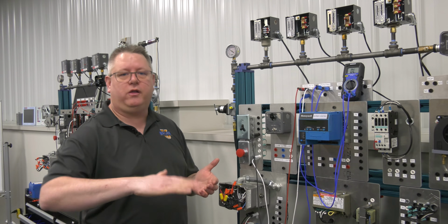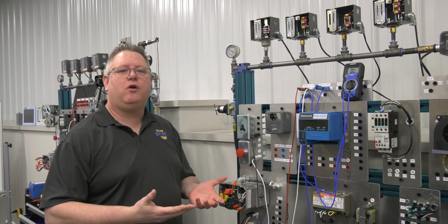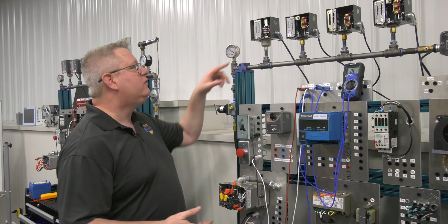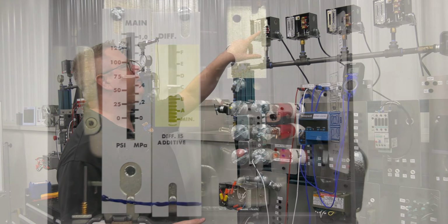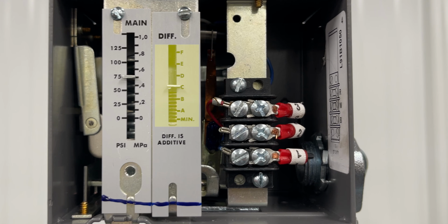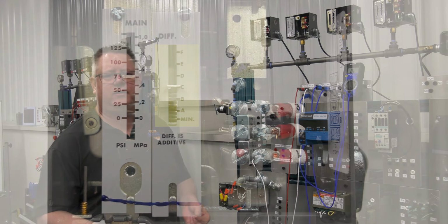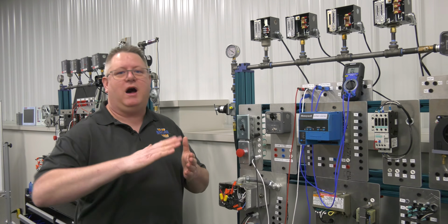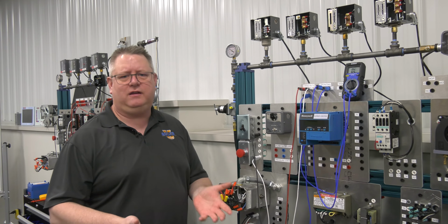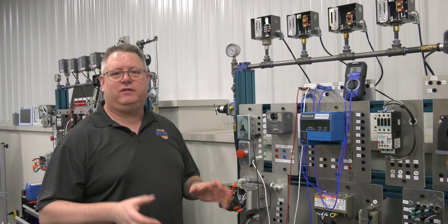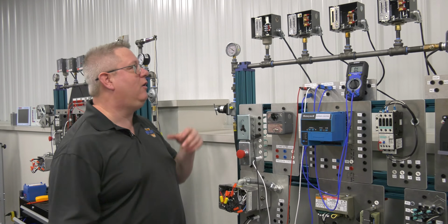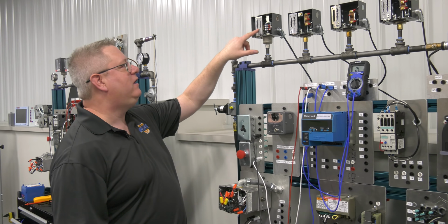Now, once we've attained that minimum, we do want to modulate the boiler down, and we want to do that over a controlled range. So Honeywell uses the letters A through F and minimum to set that modulation band. And they use letters because they're not Swiss timepieces, and they really don't want you to call them and say, well, I set it for a 10 PSI modulation band and it's modulating 8 PSI. They just really don't want to hear that. So they use letters instead.